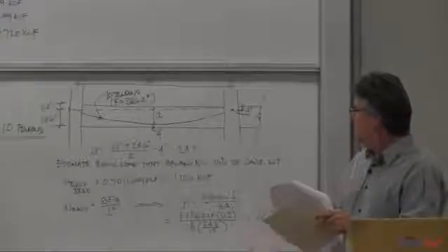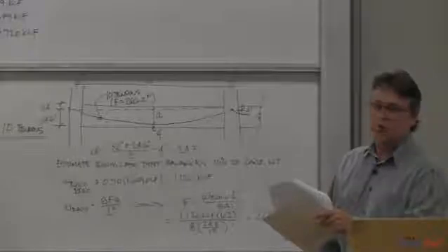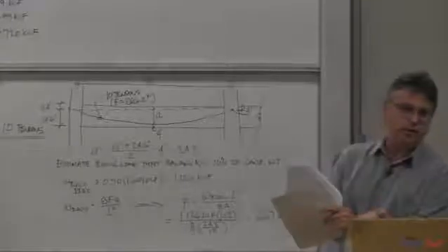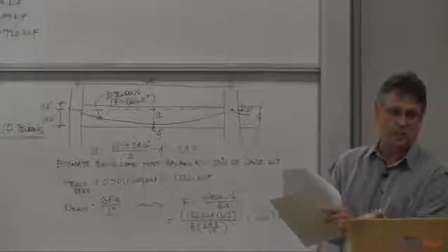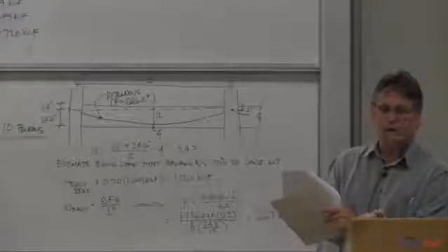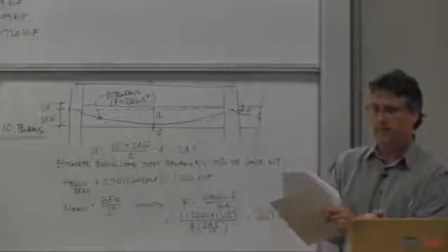We could just, if it's in between, add a strand and then change the drape. You'd never want to change the drape. The drape comes for free. So you take the whole drape in the controlling span. And remember, tendons cost money. So you'll start with which one? The lower or the higher? The lower. Then if you've got to add money, you add money when it doesn't work.